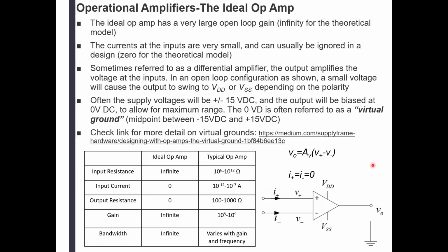We call that infinite gain. So, does it mean that if we have 5 volts, then it's going to take this thing to infinity? Well, if we had the infinite power supply, yes, it would. But it's going to go only as far as the power supply is going to let us, right? So it's going to go right to the saturation point, to the plus 15 volts.